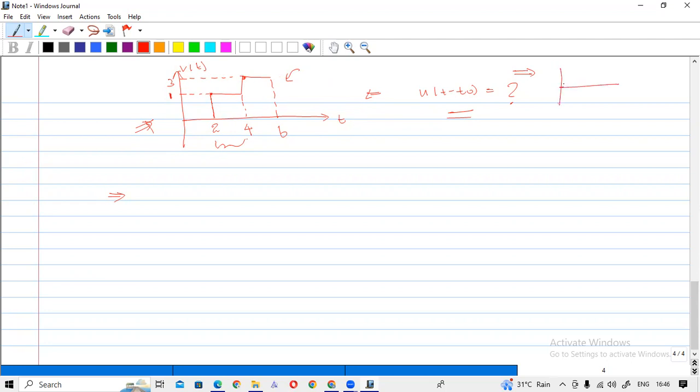For example, if you have a sinusoidal signal like this, you can represent it like this. It is not completely correct, but you can get the shape, no? So this approximated staircase function, you can represent using shifted and weighted unit step functions.